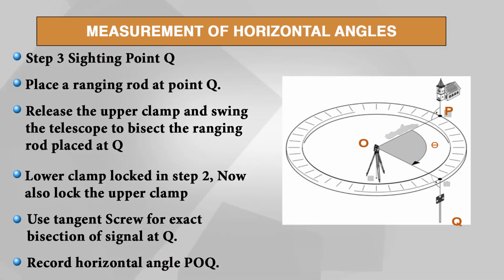In this, we are repeating the same measurement 3 times with face left and 3 times with face right. Now, when we come back to point P again, we will find that the reading is not 0; it is actually equal to the angle measured in the first cycle.